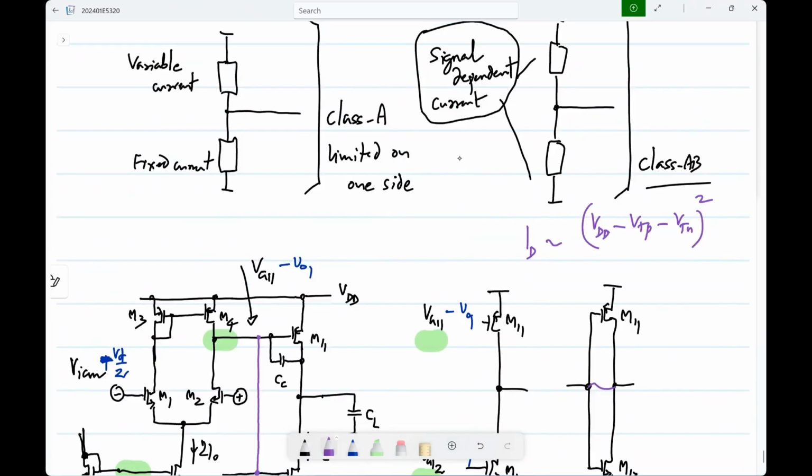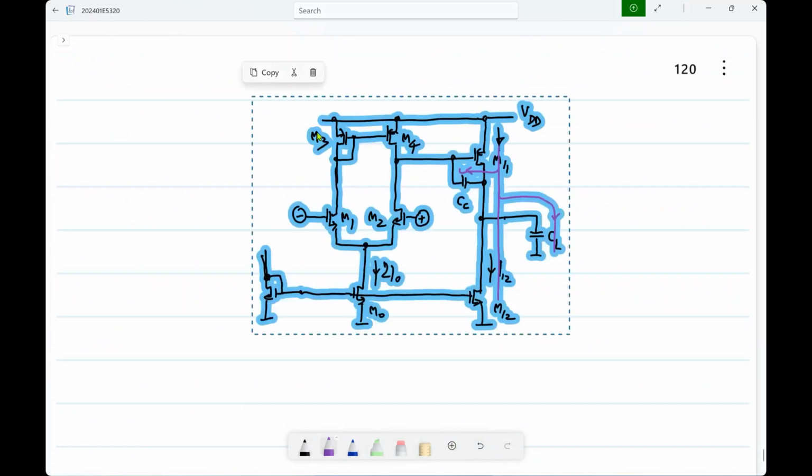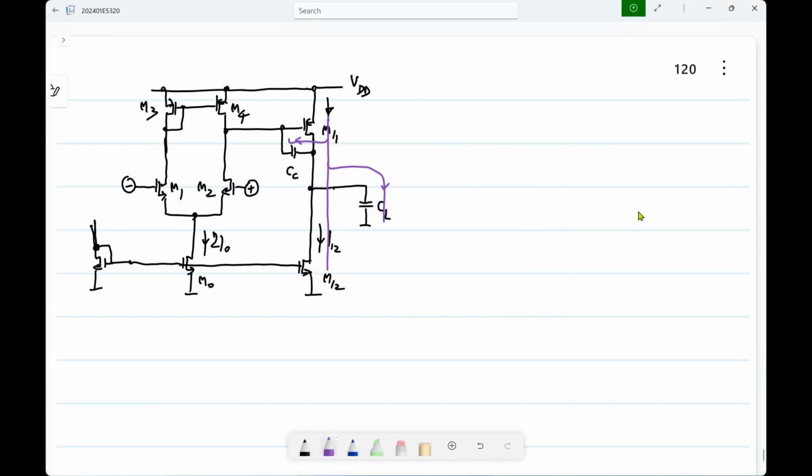So this will deliver the signal to both stages, both PMOS and NMOS transistors, but it doesn't have a well controlled bias current, and it also has the swing limit issues. Okay. So what else could we do? Actually, it's not that simple, because you would like the voltages to be the same, but you don't want this uncontrolled bias.